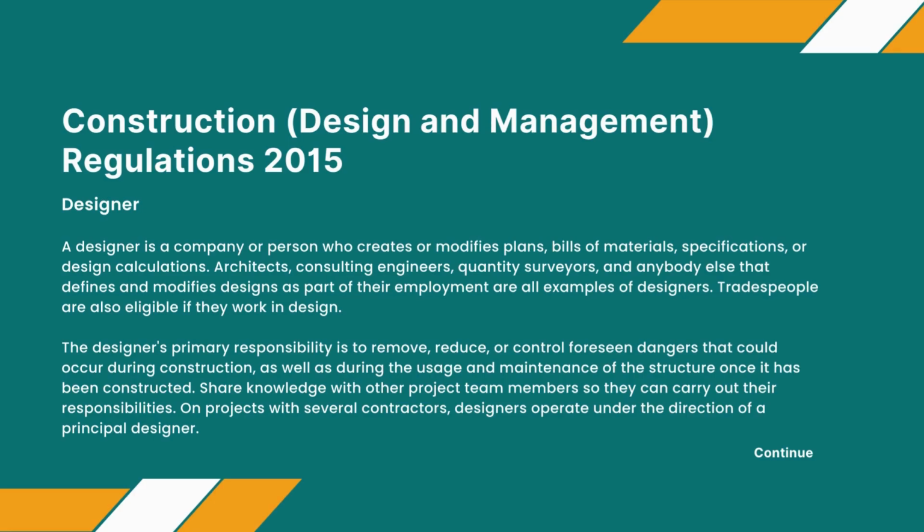The designer's primary responsibility is to remove, reduce, or control foreseen dangers that could occur during construction, as well as during the usage and maintenance of the structure once it has been constructed. Share knowledge with other project team members so they can carry out their responsibilities. On projects with several contractors, designers operate under the direction of a principal designer.